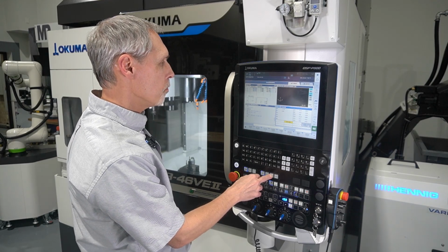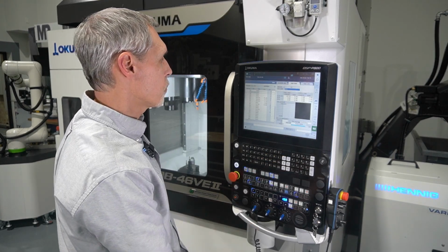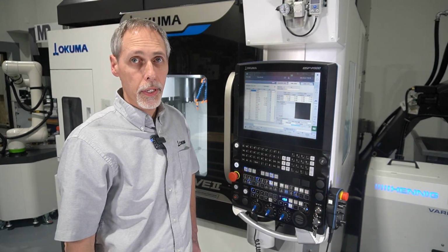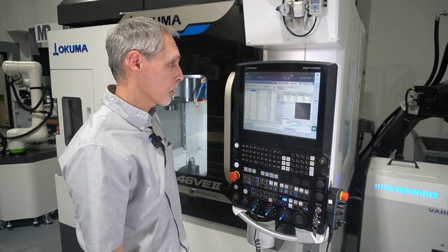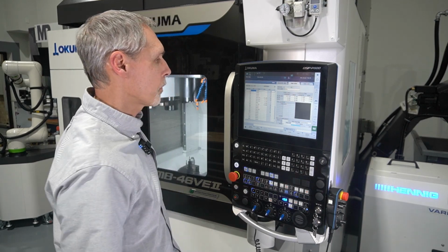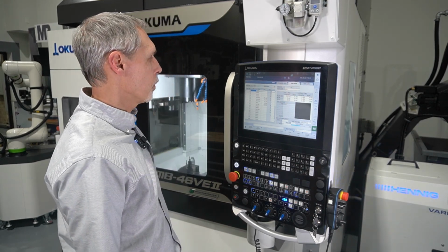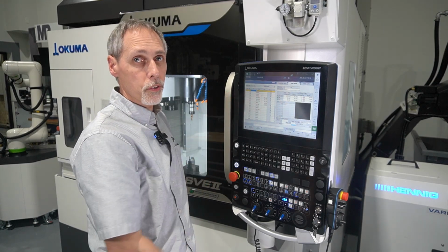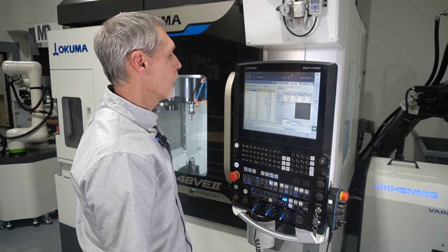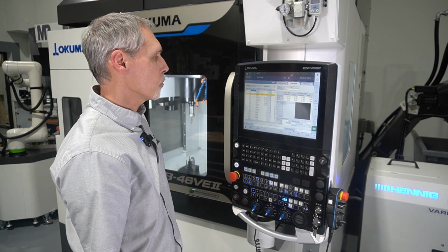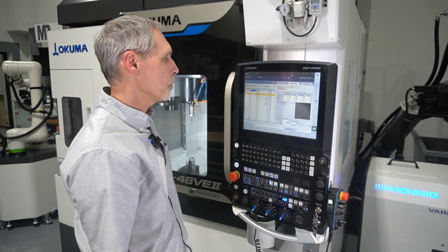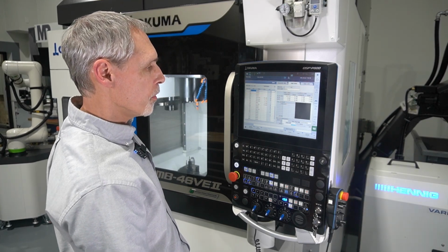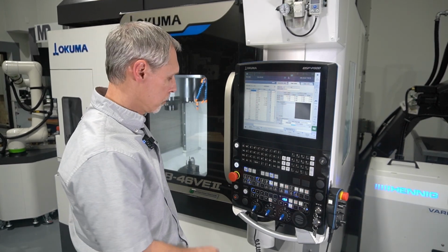So I've run it one time and we're going to see that on our tool 150 that the left value now went from 3 down to 2. That's what we expect. Let's run it again. It's going to go get my tool 150. We can see on the screen the yellow bar indicates that's the tool that's in the spindle. It's going to change to tool 160. We're not using Tool Life Management on that tool. My counter for 150 went down. Now it's down at 1. We're running it again.